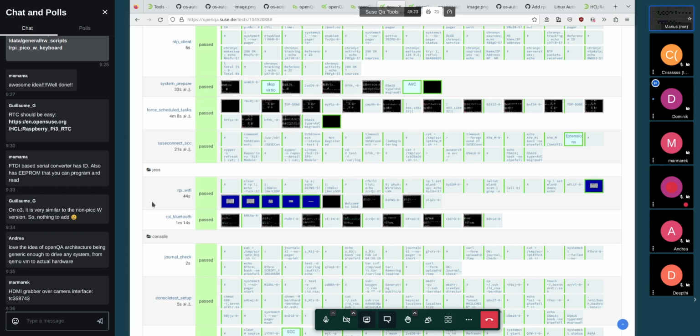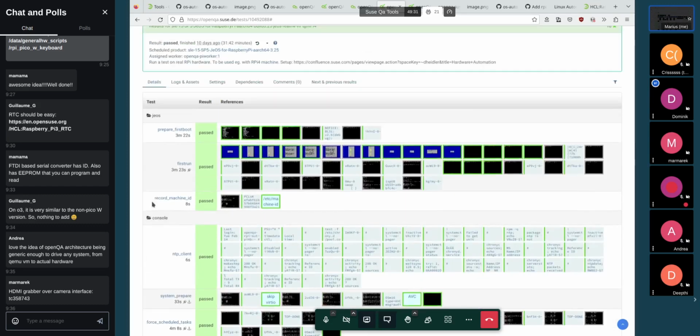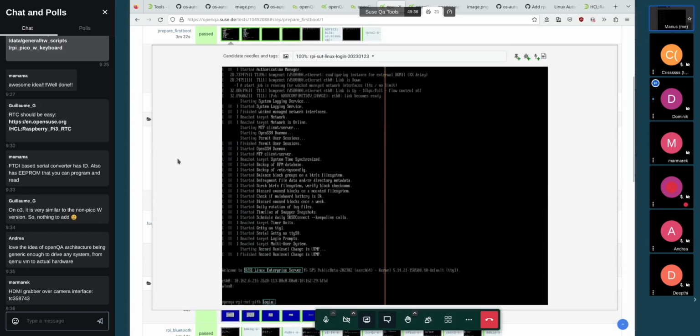When I boot the system up, I can see at the UART console that the log is already there, that the system is already booted up and there's already the login prompt, but it takes a few more minutes until I get the video output of the login prompt, or even the boot up. So essentially, I seem to have quite some delay there, and I haven't found out why.